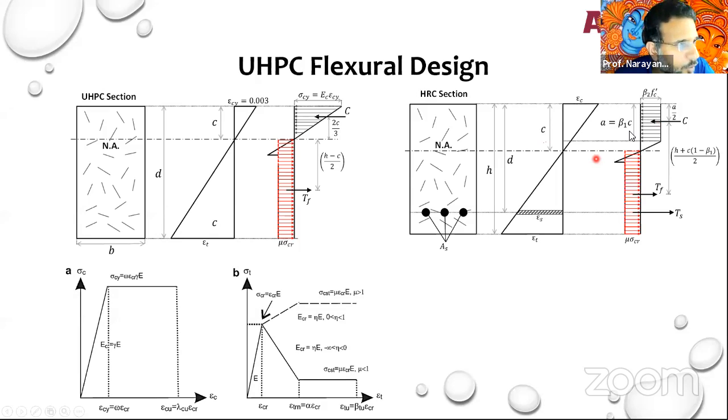Now, if I take the moments of all of those, the moment capacity of this beam is going to be much higher because the fibers contribute a significant amount of tensile force. So I get a much more improved contribution. This entire zone below the neutral axis that would have otherwise been wasted is now being efficiently utilized with steel fiber.